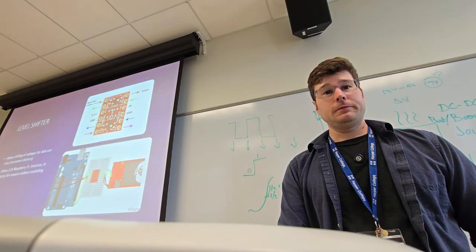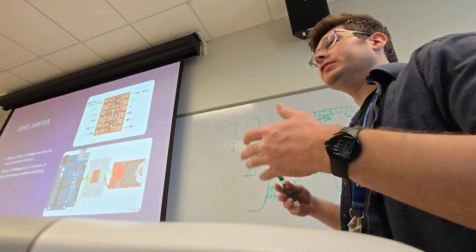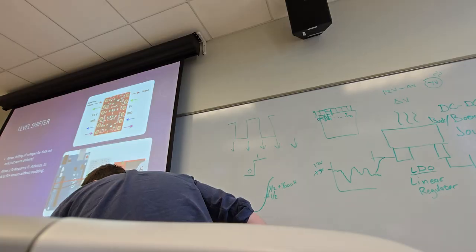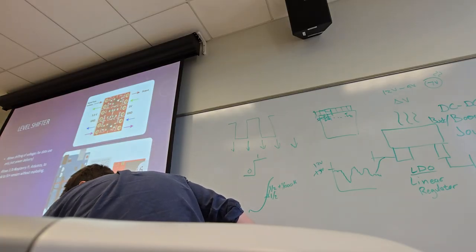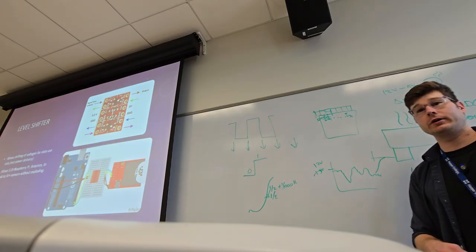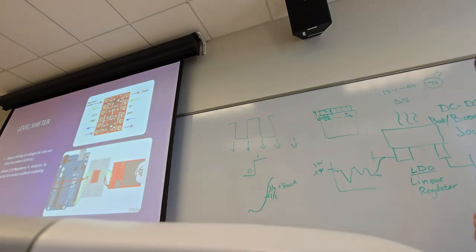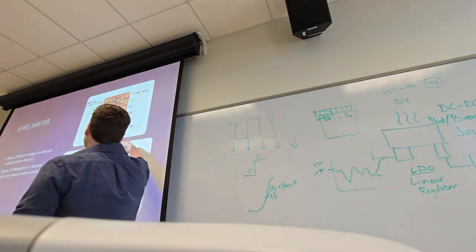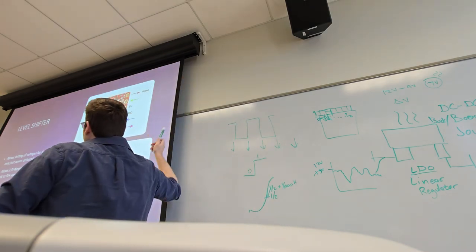I'll go back to that in a second, but one thing I want to talk about is data voltages that are different. For example, sensors, right? If you have a 12 volt sensor and you try to wire that into a 5 volt Arduino, you're going to get some smelly white smoke pretty fast. So how do you deal with that? You use this device called a level shifter. These are also like 50 cents each on Amazon. They come in packs of 10.